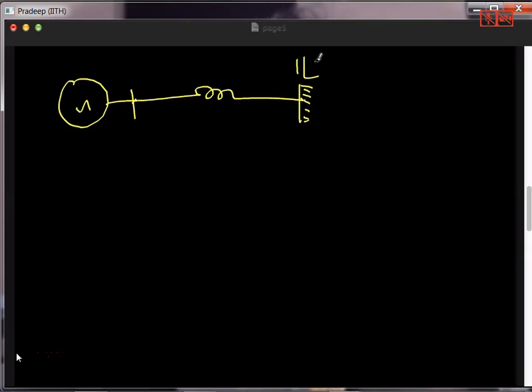So this is one angle 0 degree. This is some reactance X, and this is my EMF induced, and this is my angle delta. So consider a generator whose output voltage is this one. Remember, sometime back we solved a problem, two sources connected by a single resistance, single reactance, so two sources connected by a line. That is what this is.